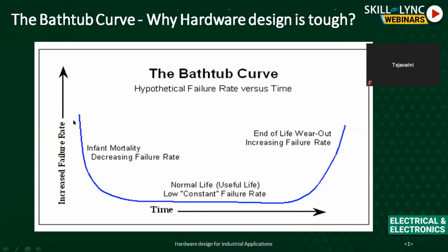Infant mortality. During the infancy stage, if you get failures, that is still fine, and naturally it is going to be more. And once it is in the field, it should not fail with respect to design. Because assume that if the product fails from the engineering point of view in the field, then the customer can take legal action. So it should not fail in the field at all. So here there is a very low failure rate during its lifetime. And finally, once the product passes its lifetime, then it will fail because of aging and wear out.